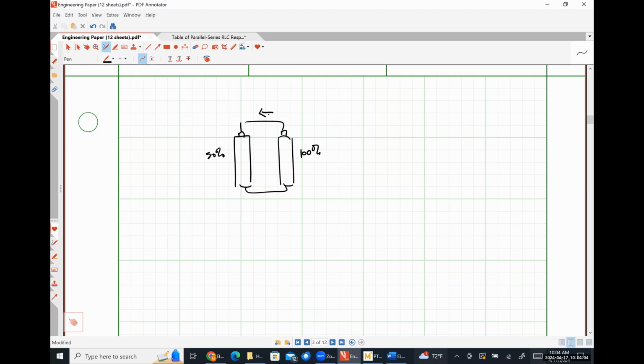I think it's a P-type crystal, then a metal, then an N-type crystal, then a metal, and then a P-type crystal and so on. So you're using thermal coefficients of the metal junctions so that when you heat up one side of this thing and keep the other side cool, the temperature gradient winds up inducing a voltage across the device. You should have learned about that in 334, I think.